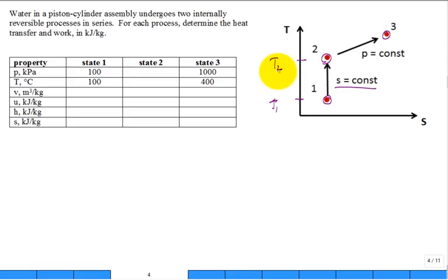And no irreversibilities, hence no entropy generation. Both of those combined from the second law show it's isentropic, same S. You want to see it in equations? S2 minus S1 is equal to, let me write it as, Q 1 to 2 divided by T plus sigma 1 to 2. If there's no heat transfer, and if it's reversible, it's isentropic. Big conclusion. But how did I get the temperature to go up? Well, you can put in a lot of work. And there's no entropy transfer with the work. But when you put in the work, the internal energy goes up, temperature's up.